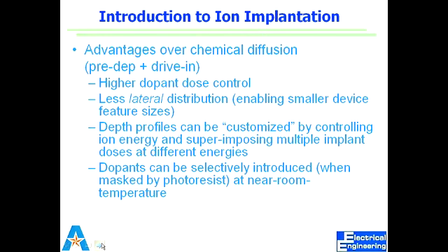So when you say multiple implants, in modern devices we don't have just one doping in a device region. We have multiple regions of doping profile. And part of the reason is to get rid of short channel effects, to alleviate the issues that come with the very miniaturization of those devices. So